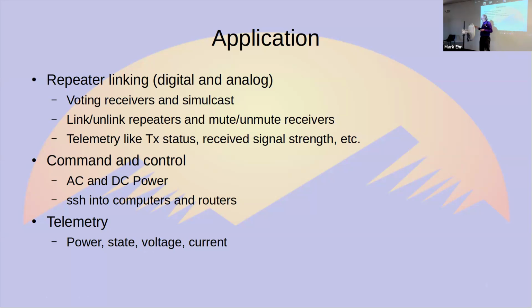So there's actually on the mounting hardware in the back here some fine adjustments so that you can actually move it in very small increments, which really helps to actually get the link properly peaked both in the horizontal and the vertical.